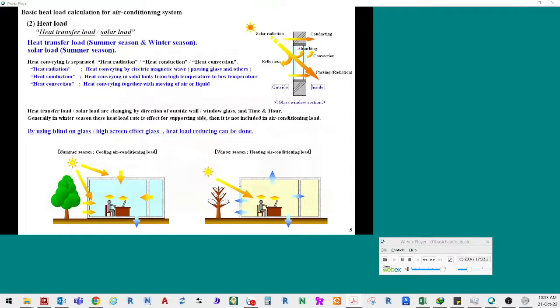Under air conditioning, the temperature of the ground is lower than the room temperature. The heat escaping through the earth's floor in the basement walls not shown in the drawing is a factor in heat loss. The escaped heat acts advantageously for the room during air conditioning, so it is not considered as a heat load. During heating, however, it is considered as a heat load. During heating in winter, however, the solar energy acts advantageously for heating, so it is not considered as a heat load.